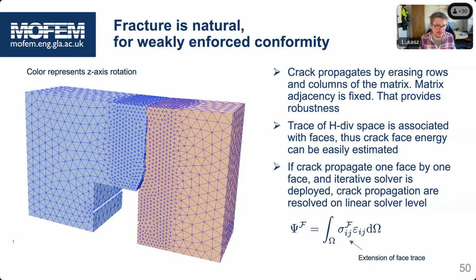This is under testing by our colleagues in the industry, and this is one of the tests they are running. You can see that the simple idea of breaking faces by removing rows and columns, and adjusting the face position to maximize this function, works pretty well and gives us crack paths which match reality. Later on, supplemented with h-adaptivity with hanging nodes, and scalability, it could be a really powerful tool.